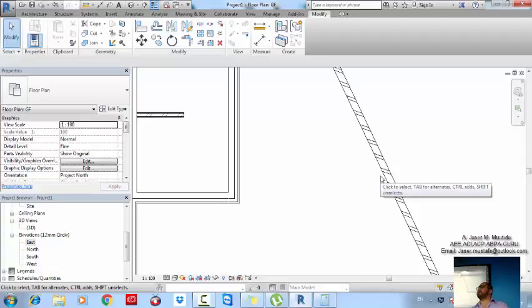What are the layers? The core of the wall, which is concrete. And the external would be stone. The exterior finish is stone. Yes. Inside would be an air gap. After that, brickwork. After that, the finishing, which is maybe plaster and paint, maybe gypsum board and paint, according to your design.